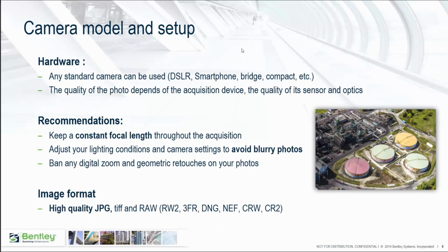We have a few recommendations for taking photos. And first would be to keep a constant focal length throughout the acquisition. You are allowed to change the focal length if it is to circumvent a limitation. If you want detail, you can get close to the scene. But at least don't change the focal length for each and every photo.